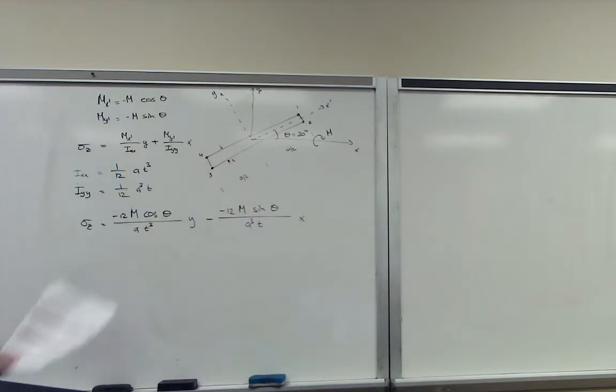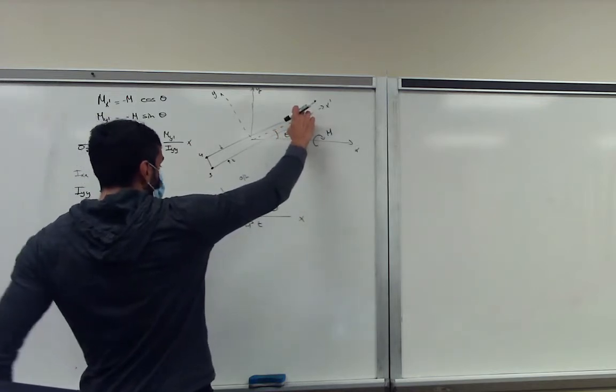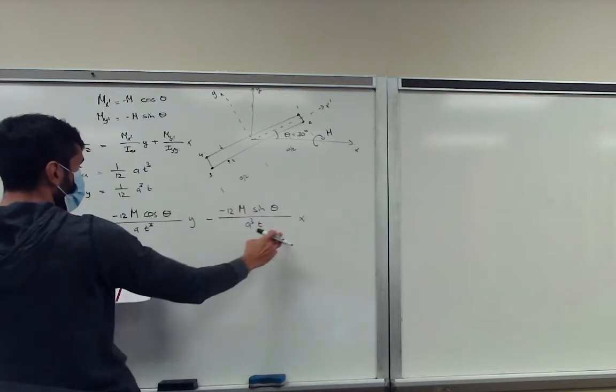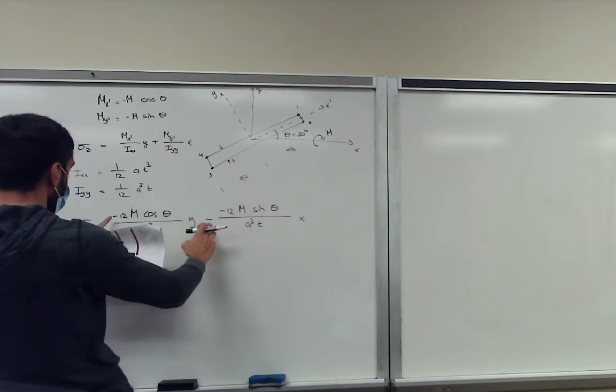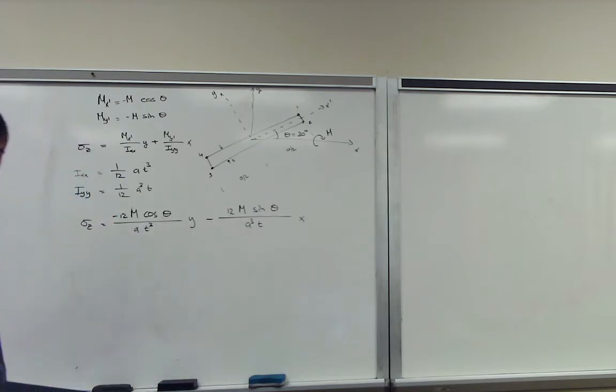Based on our equation, we can already determine that the location where both are positive will become most negative. And at the location where both are most negative, these minuses become pluses, so our stress will become maximum. So again, why do we need both maximum and minimum stress? Because in some materials, the maximum stress in tension and compression is not the same. So you have to double check both.